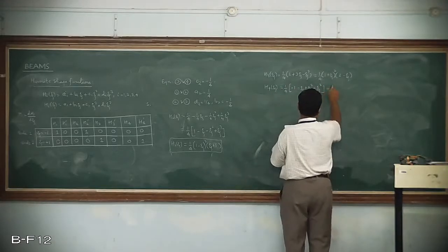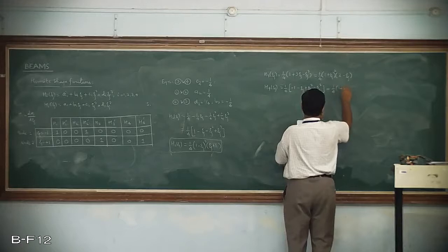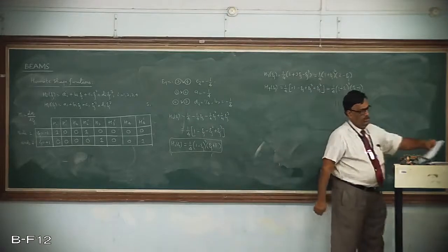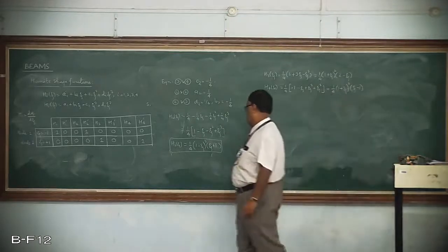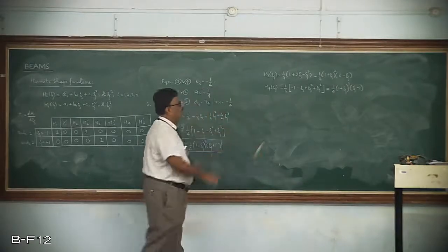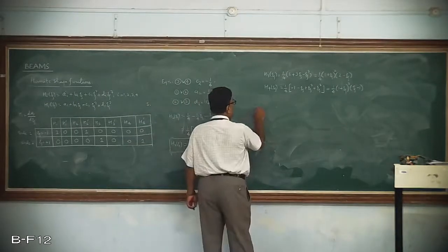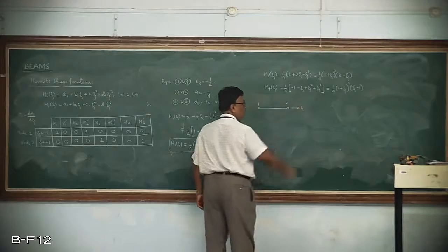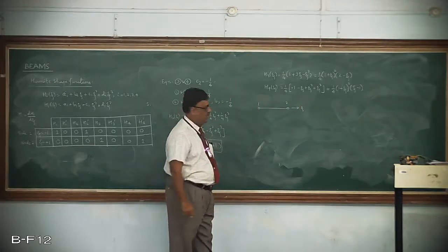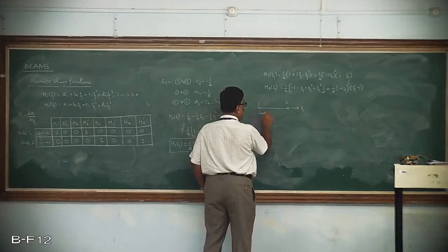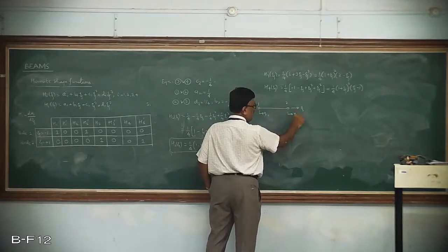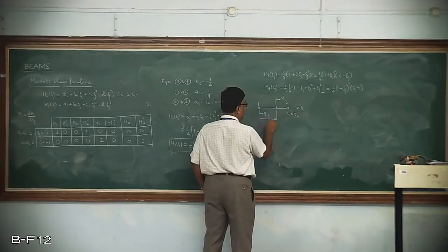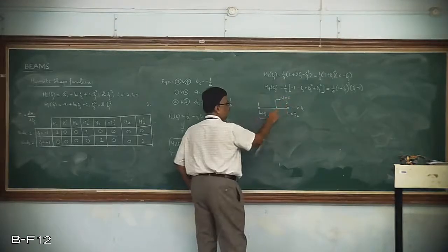And if you really write this in the form here, yes, this is going to be what is called the 4 shape functions. See, what is the use of these 4 shape functions? Like for example, I'll just tell you, if you take this as your 1 and 2, in the case of a one dimensional 2 noded bar element, what we have seen? We had seen that the displacement of this was Q1 and the displacement of this node was Q2. Suppose if I want any point where if I simply specify the value of zeta, how to find out the displacement of that particular unknown point.